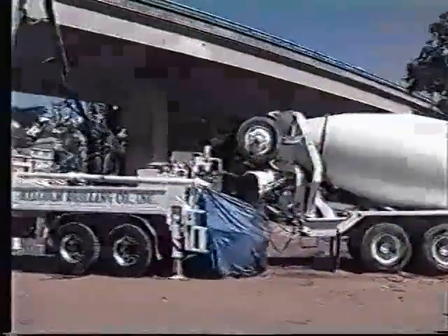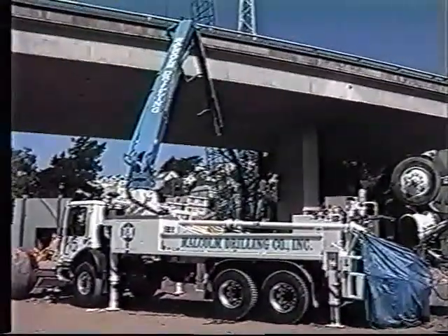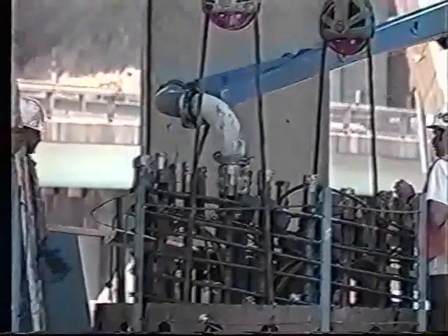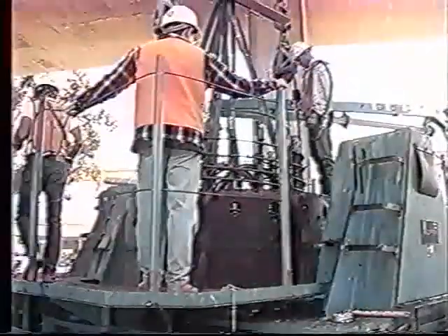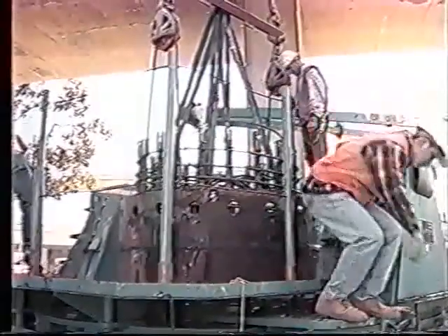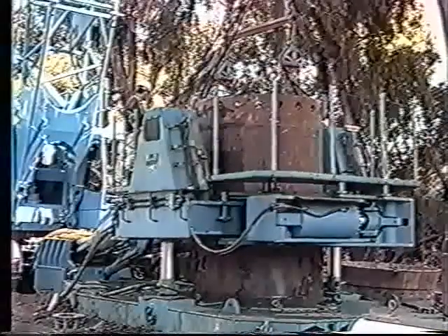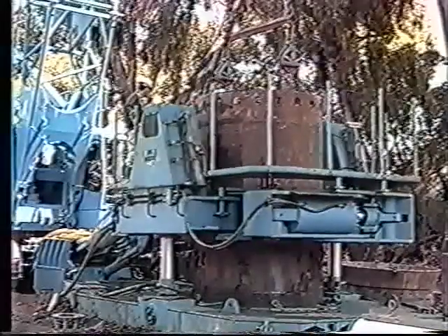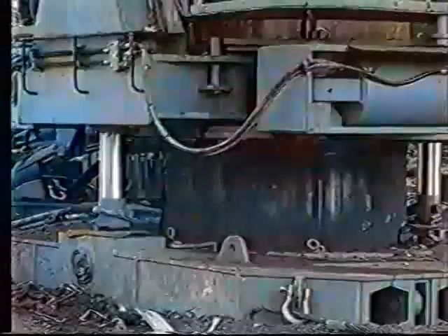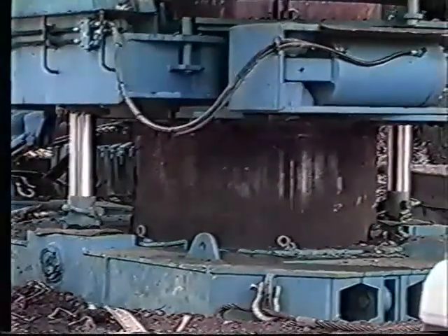Malcolm Drilling Company uses its own pump truck to pump concrete to the hole over a great distance due to the difficulty in reaching the hole. The Leffer oscillator removes the casing sections as concrete is poured. The extracting rams and torque of this fantastic machine enable it to pull out the temporary casing quickly and easily. Each 8-meter section was removed in 8 to 13 minutes.